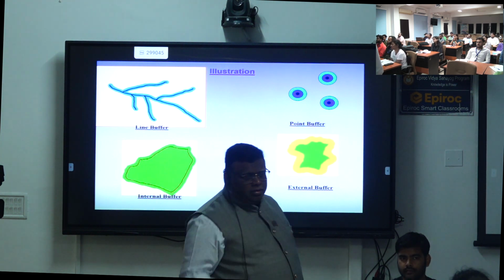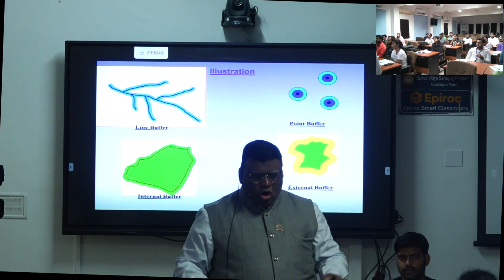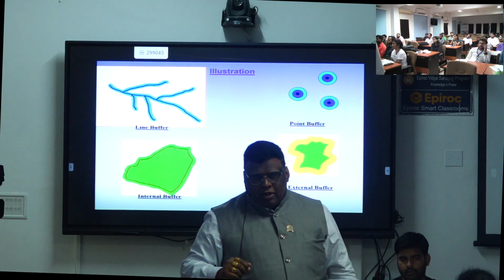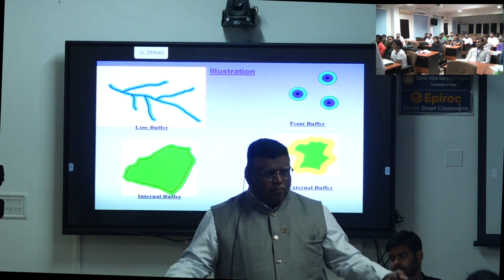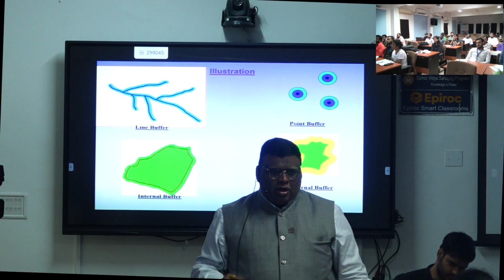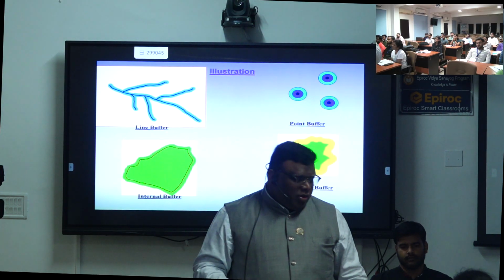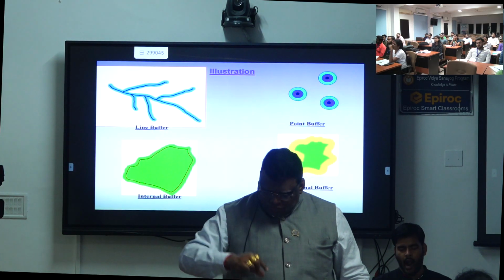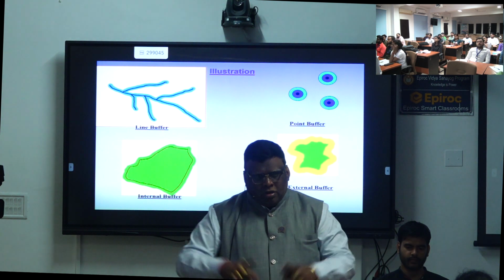A road is there, with the old city, all the shops and your buildings. You want to go from a single line to double line, or double to 4 line. Then if you start doing your survey, obviously there will be some repulsion. Then what you will do, you will get the satellite data and mark the road, and then you want to have the buffer.